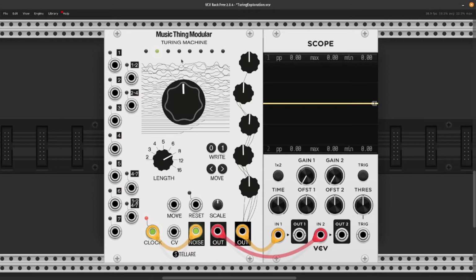It produces a random sequence by populating this byte with a randomly generated bit from the most significant bit to the least. And using a shift register, it pushes the random bit on the most significant down to the lowest significant bit.